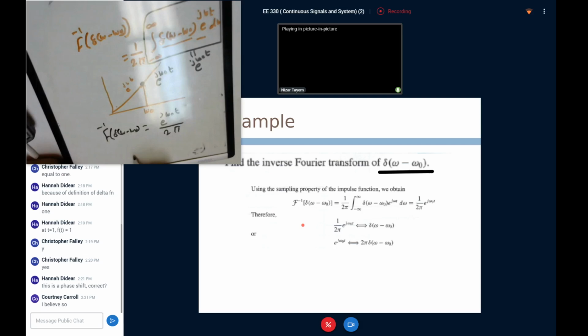What does this mean? If I take the Fourier transform of a cosine function, I'm going to end up with two peaks, one at ω0 and another at −ω0. So the Fourier transform is going to look something like that: a peak at −ω0 and another peak at ω0. These are the two peaks you have seen in amplitude modulation: one at the carrier with the upper sideband and lower sideband exactly the same. Mainly we do a Fourier transform, implemented using the FFT, the fast Fourier transform.